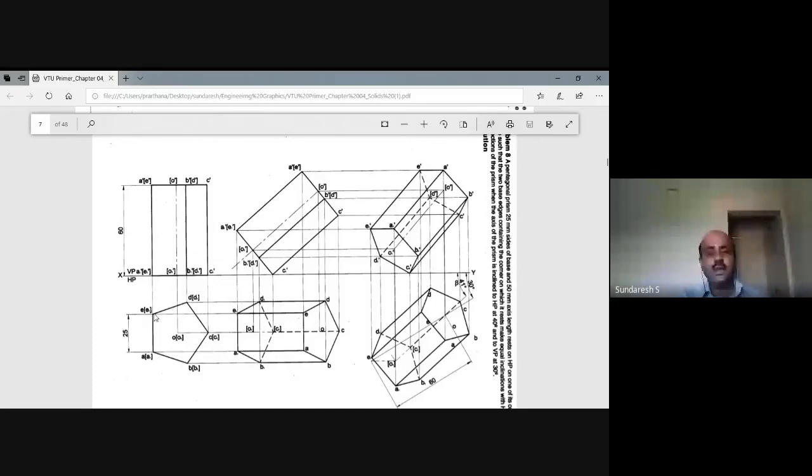So now you can get the front view for this. Just draw the projector lines, and of course, I told you to get the axis line. So how do you get the axis line? In the case of a pentagon, you have to draw a minimum of 3 perpendicular bisectors. A perpendicular bisector is a line which joins a corner to the midpoint of the opposite edge.